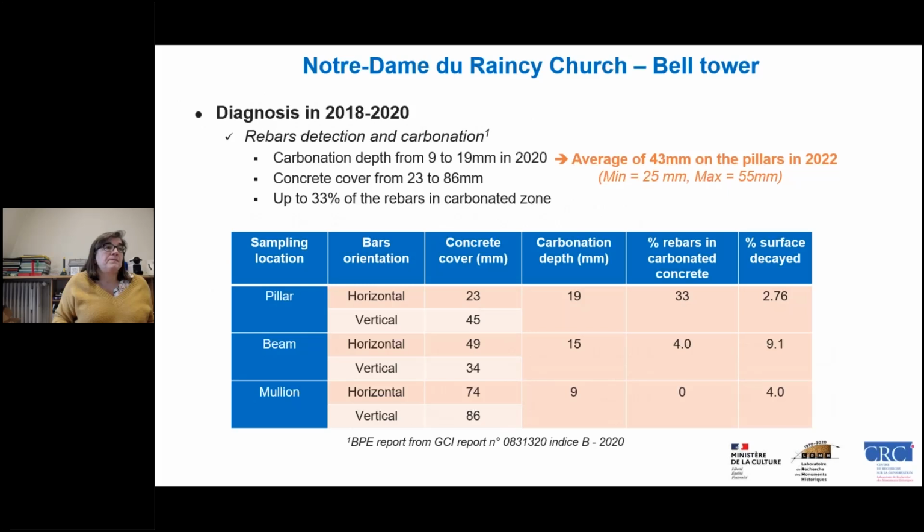And dealing with carbonation and rebars, what we can see is that the carbonation depth was ranging between 9 to 19 millimeters, so not that much finally. And we had from 0 even to 33% of the rebars in carbonated concrete.